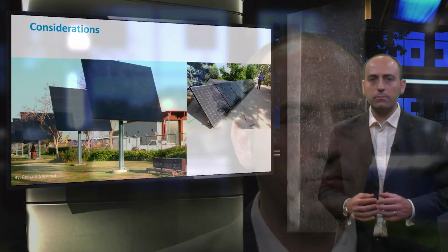Not only objects close to the system may cause partial shading, but also faraway hills or mountains may obstruct the direct sun irradiance falling on the modules. Hence, during the design, it is important to evaluate the impact of each possible source of shading for all months of the year. This is the task of a PV system installer, and you should be able to tell if shading will be a problem by using a range of mapping tools.